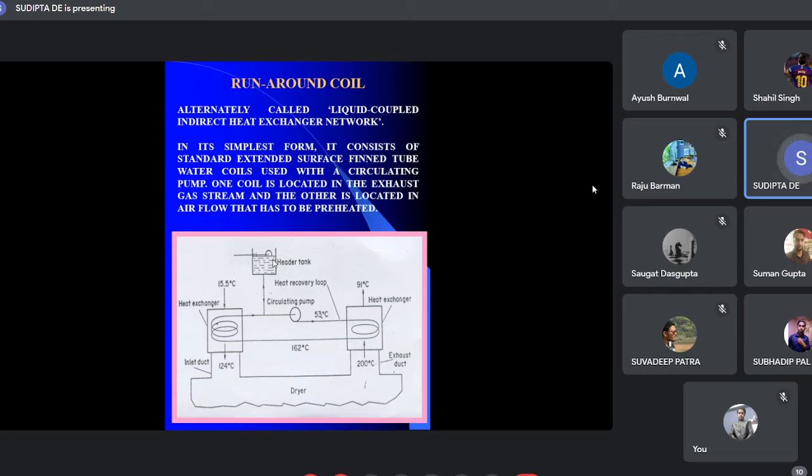So, if the pressure drop inside the pipe is more, then that has to be paid against the electricity consumption. And you need to have sufficient heat exchange in both the ducts. Based on that, this is possible only if the available two gases at different temperatures are not at quite far off distance. Otherwise, the corresponding heat loss and the pressure drop both will be significant.